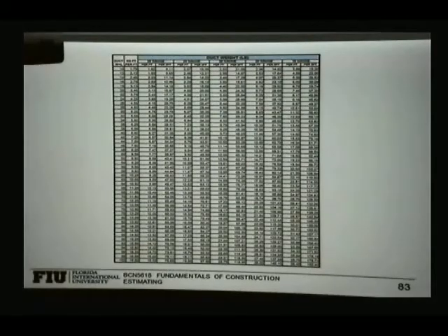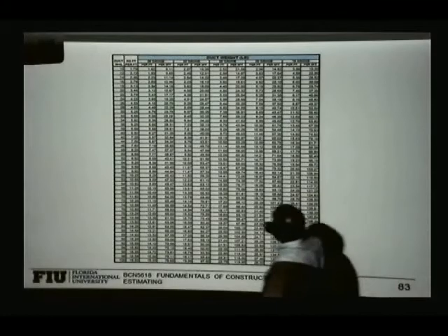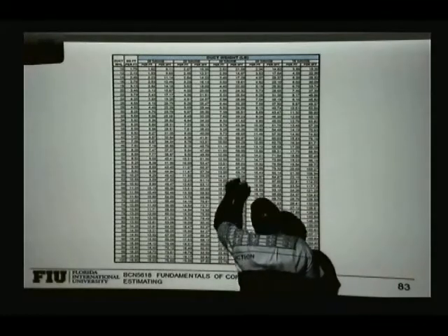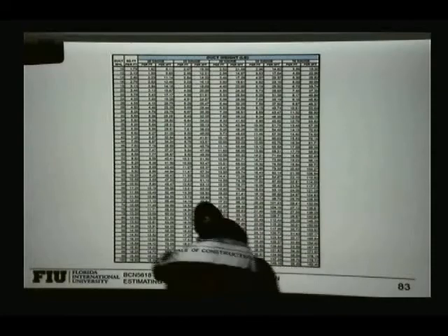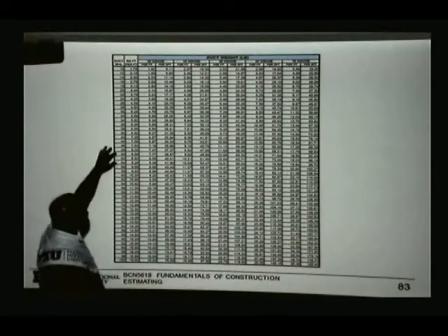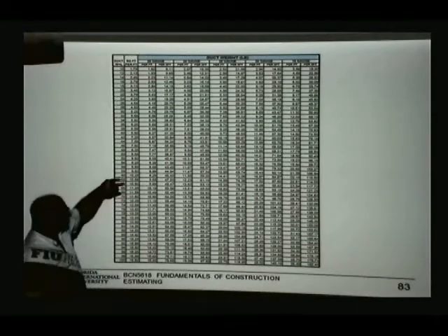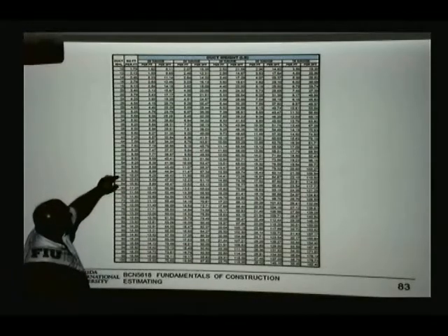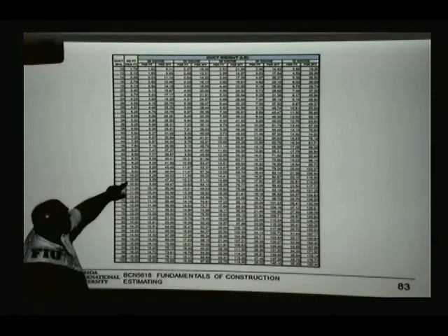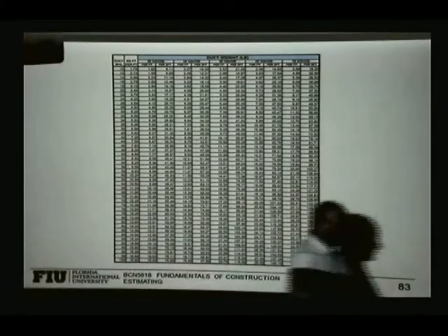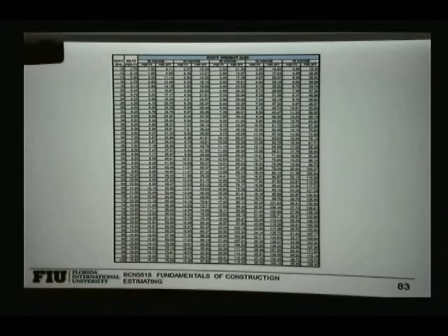Here is a table that shows, kind of difficult to see, but this shows the weight in pounds per linear feet. So you have the duct, what is the dimension of the duct, length and height, and then that will tell you what is the square feet per foot, and depending on the gauge, the thickness of that duct, you get the weight per linear feet.